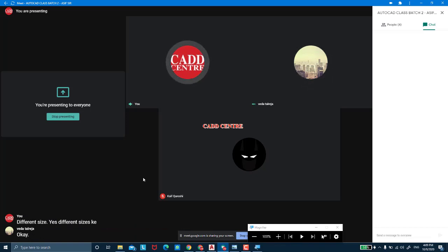So what you're going to do is create windows of different sizes. I'm going to give you these: one is 4 feet in length and 9 inches thick in total. One is 5 feet and 9 inches thick. One more is 4 feet in length and 4.5 inches thick. Then again one is 5 feet and 4.5 inches thick. The settings for the attributes would be the same for the rest. Attribute settings would be the same.